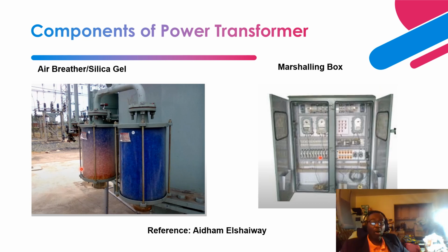So this is where all the wiring of all the auxiliary devices can terminate on a terminal block over here. And from here, it is wired to a local HMI or RTU or to a SCADA system, depending on your communication scheme.